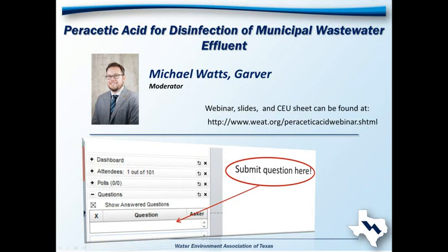Okay, and then there's another question that came in. This might be for the entire panel here. With the reduced effectiveness against viruses, I think that's PAA against viruses, is there discussion of TCQ changing the indicator organism? And Mike, this is Carl, and I'd like to just mention something there as well. There aren't a lot of data actually on many different viruses and disinfection of viruses with PAA. So I think that's an area of research that we need to think about beefing up. Certainly we know the indicator organisms are disinfected, but I think it's a really good point the questioner makes. Considering the lower efficacy against some viruses, as well as some spores and likely Cryptosporidium and Giardia by PAA, to what extent might there be a better indicator organism? But certainly, for regulatory compliance, we know we can meet that, but that might not answer all the questions. I think there's still some more research that needs to get done in that area of pathogen inactivation in wastewater.